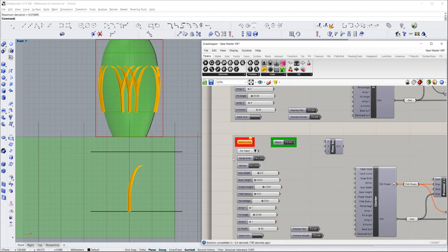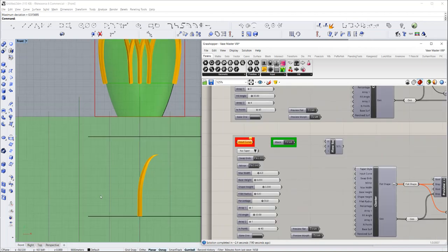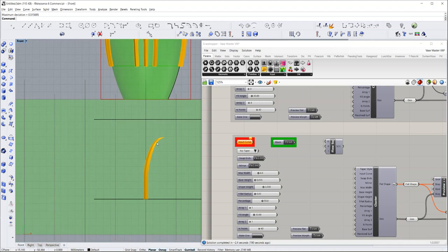And of course, I'm up here and I need a curve. Well, let's do something different. We've been dealing with our tapered curves and things like that. What I would like to create here is a closed shape, and let's do an ellipse. We'll do an ellipse by doing a diameter, and we can move this around. So let's start here and just come up with a size we'd like. Hold the shift key down so I get it truly vertical, and then open it up a bit,